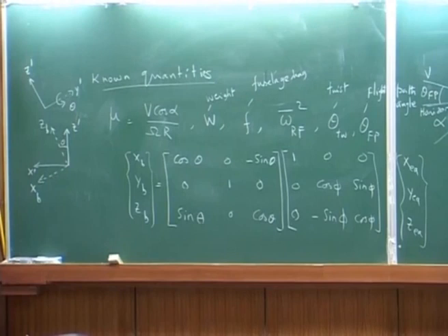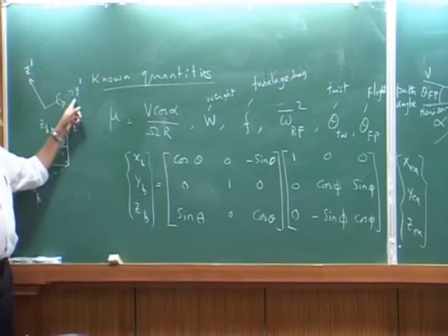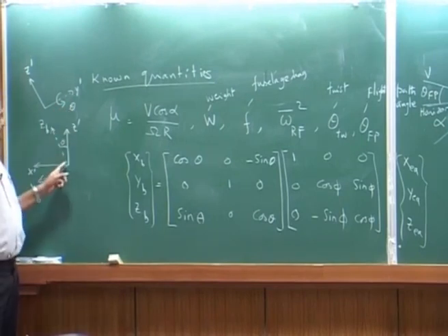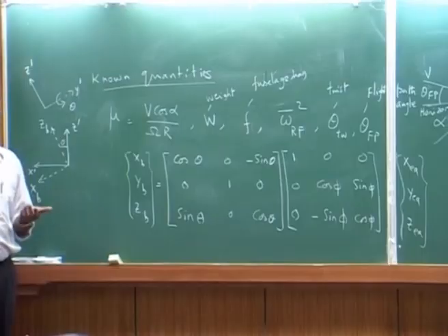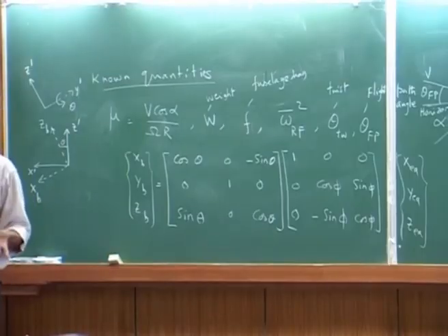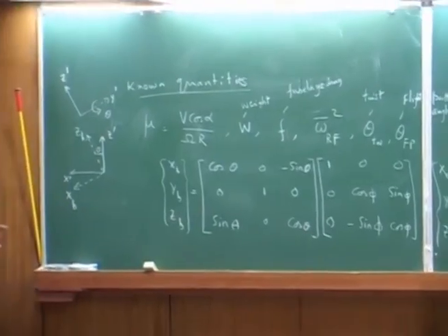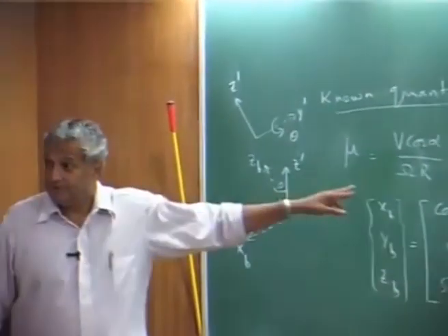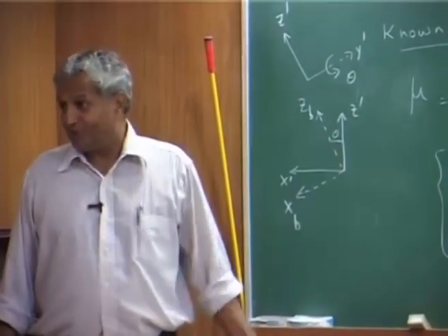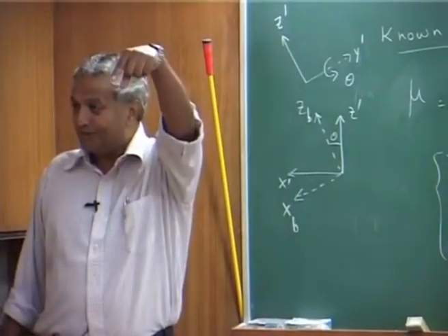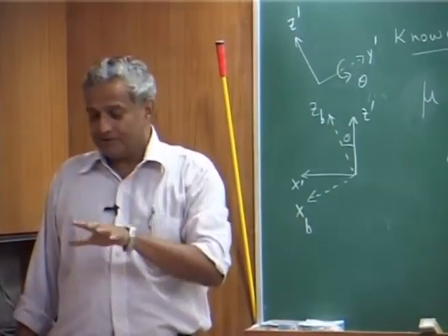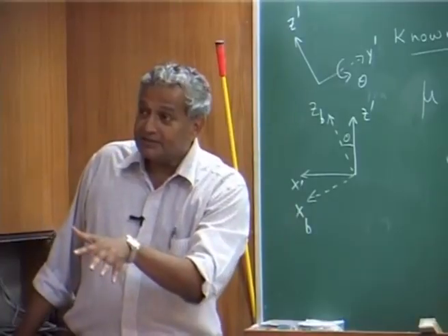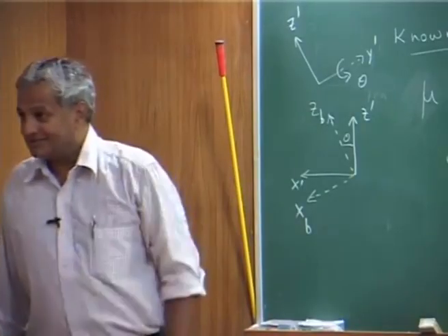You follow? Because you see y prime is nothing but y body, right. So, basically theta dot becomes the pitch rate, whereas phi dot is not exactly the roll rate experienced by the gyro on the vehicle. That depends on what is the orientation of the aircraft at that instant.